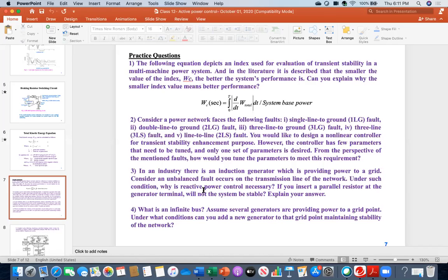In this case, already there is a capacitor connected at the terminal, even at the steady state. During fault condition, you need to provide an additional reactive controller, and typically you will connect that at the grid point. It is not like you will be making it grounding. Of course, because this is connected to the grid, definitely you have the transformer, and the transformer has the neutral connection.